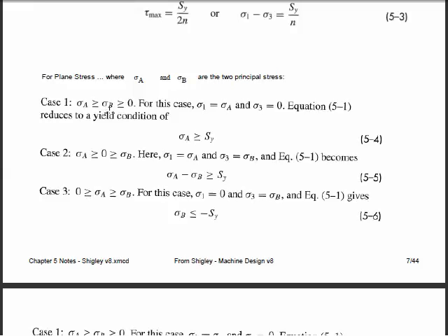Right now we're not looking at the three-dimensional circle. These cases take into account the three total circles for us. So if we just follow the rules here, we will reach the right answer. And so, if we have a state of stress, possibly given by a sigma x, a sigma y, and a tau xy, we must first do Mohr circle and turn it into a sigma A and a sigma B. Let's take a look at that. I think I've got it right here.